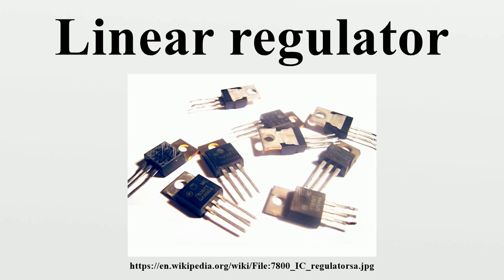For output voltages not provided by standard fixed regulators in load currents of less than 7A, commonly available adjustable 3-terminal linear regulators may be used. The LM317 series regulates positive voltages while the LM337 series regulates negative voltages. The adjustment is performed by constructing a potential divider with its ends between the regulator output and ground, and its center tap connected to the adjust terminal of the regulator. The ratio of resistances determines the output voltage using the same feedback mechanisms described earlier.